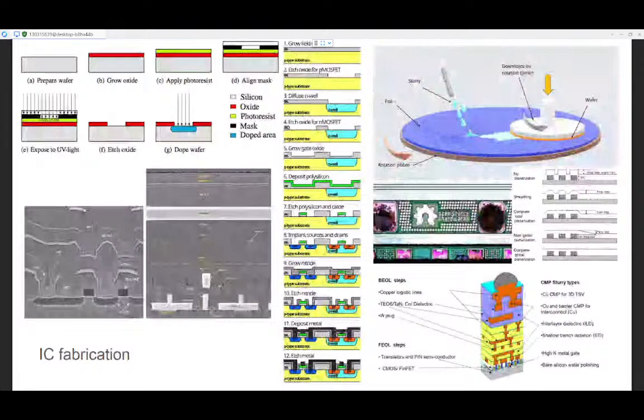Now you have two problems with that. This mechanical, chemical polishing process injects a lot of charges, static electricity. I mean, if you rub something, you get static electricity. So if, part way through building this, you have wires that eventually will be connected, but right now they're hanging in the middle of the air, we call that an antenna. When you start polishing it, that charge will go into that and burn it. So you have to protect the transistors from that process. And another thing is that if the metal is too far apart, when you try to polish it, it will bend in the middle. So any time you have some space, you have to put little squares to fill in the space.